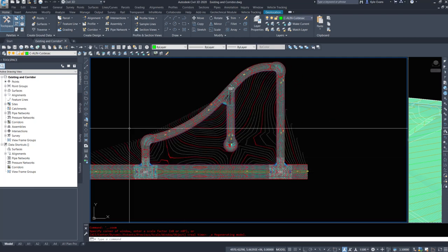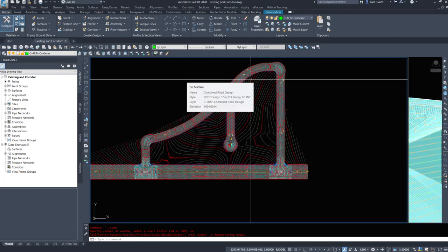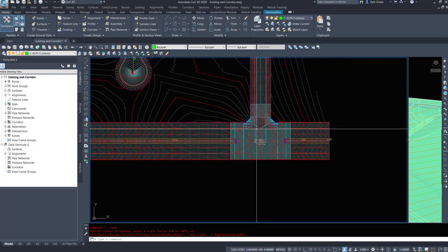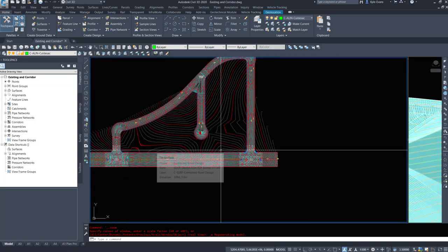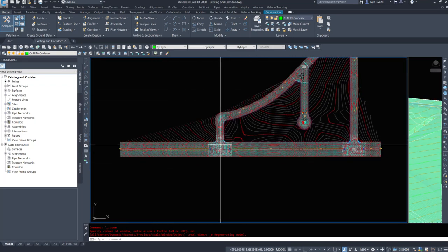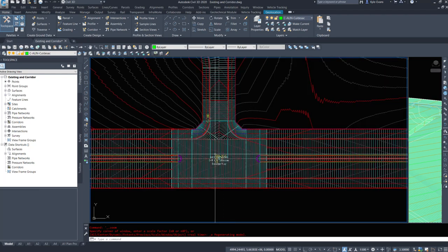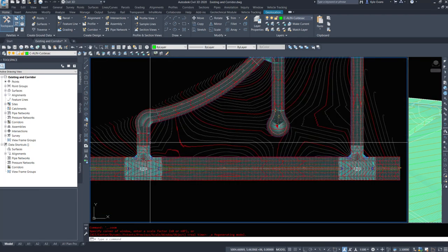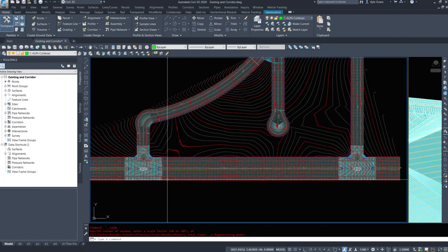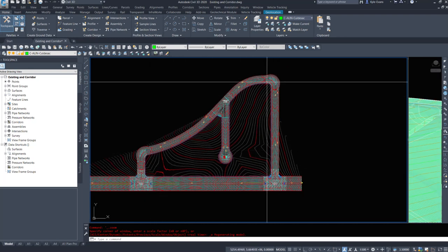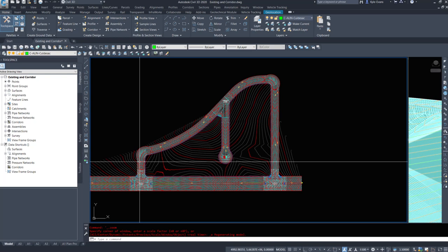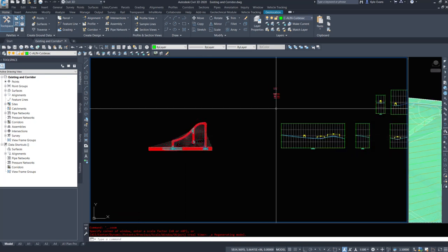Now, the biggest challenge of corridors is the targets themselves. So when we design something, what do we target? How do we target? Where do we target things? What do we name the objects? Thankfully, the intersection tool now handles most of this for us. However, there is a related issue in Civil 3D where it stretches the sidewalk targets to the center line of other roads. So this is where all the targets come into play.